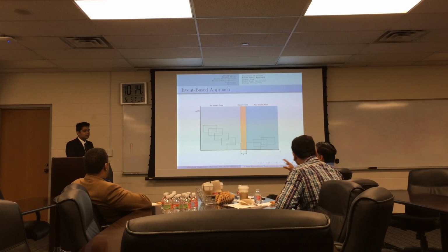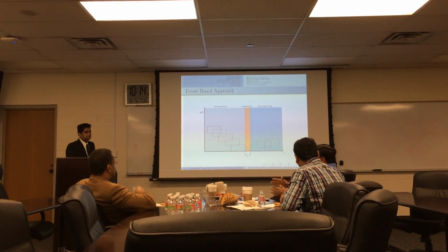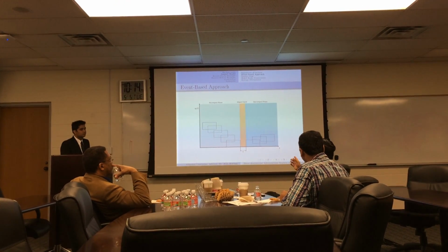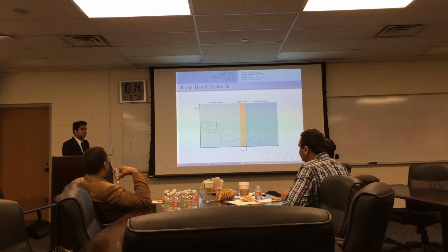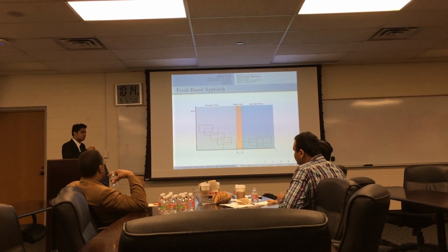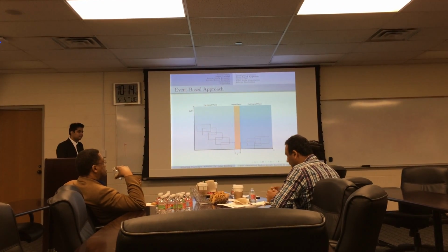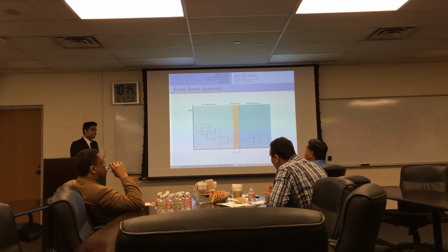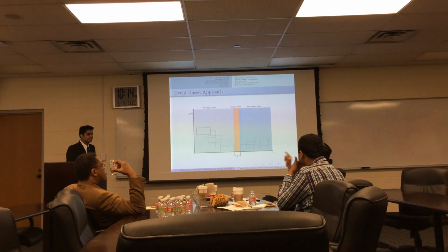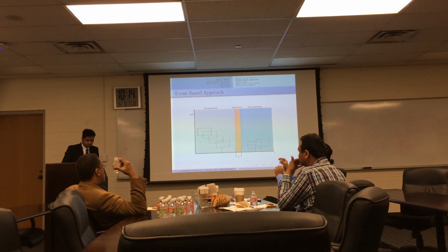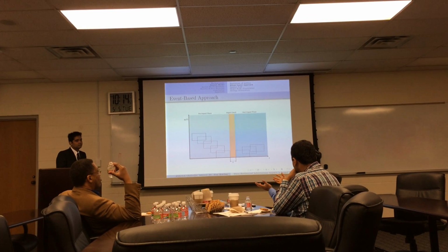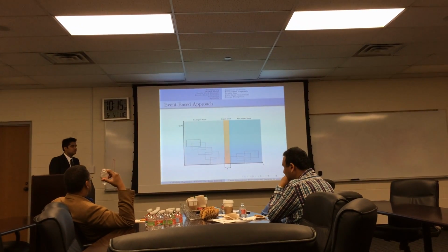Right. So I understand that. The only other question I would have on that is how do you know what points have touched the ground? And that is we will have to do a contact detection where we stop the simulation based on. In reality, the foot length, right? How do you know which points actually touch the ground? Because in simulation here, you just uniformly distribute the points. So you know the exact locations of all the points, so you can solve it. But in an actual scenario, you don't know what points actually made the contact.